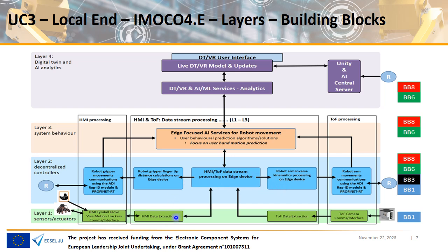So for example, we use a time of flight sensor. It's a vision camera, which is able to pick out depth fields within an image and identify a human frame, a human hand, a wrist, and also potentially objects which are captured in a frame of data. We also have a glove, which is used for very fine-grained manipulation of a robotic finger, robotic arm. Sorry, I should be saying a robotic hand, because you have the finger manipulation on the robotic hand.